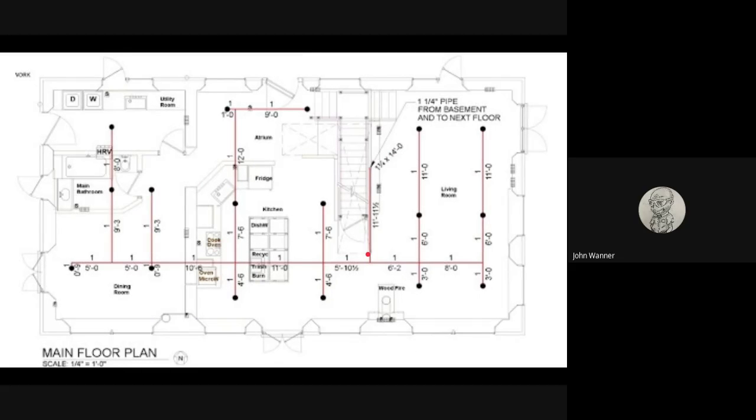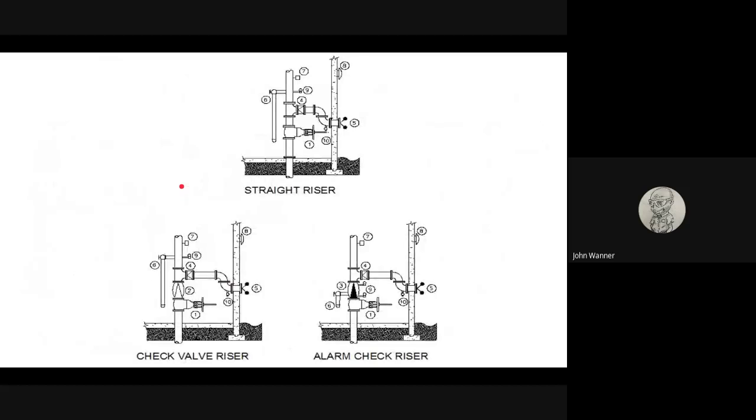One more set of plans that you will see really common, especially in commercial buildings, is the fire suppression plan, also sometimes known as the fire sprinklers. You see these red lines and then the black dots. The black dots are the fire sprinkler heads that you see in the ceiling. If you look up in the classroom, you'll see that. And a lot of times these are drawn in green, is the way I mostly see them. And it gives you general distance. Again, it's overlaid on a floor plan, and it gives you some differences and distances. And in this one, you'd have to refer back to specs to see exactly what type of fire head, what size of pipe you're using, things like that.